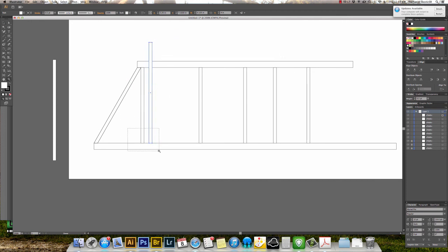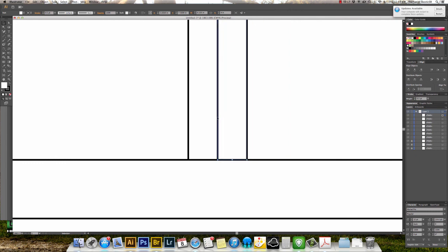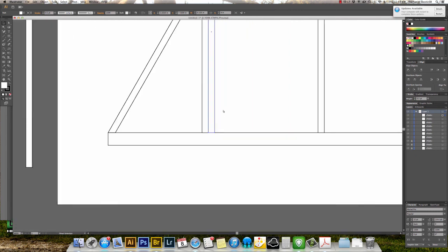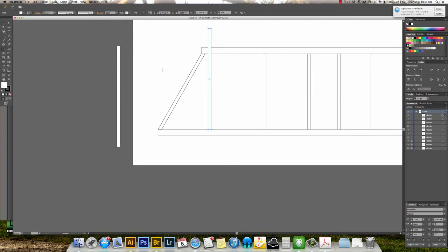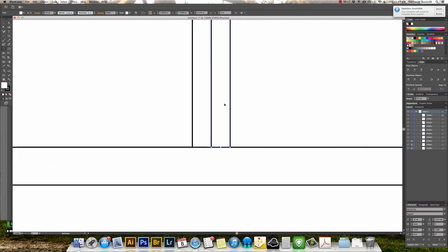Zoom tool, grab it, and put it so that it lines up where you want it. Then zoom out, go to your rotation tool, grab that, your origin, command plus, and put that origin in that corner where you want this to stay put, the spot that you want it to revolve around.